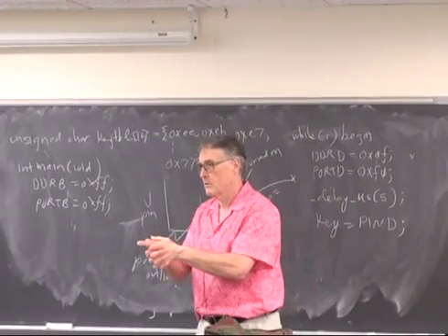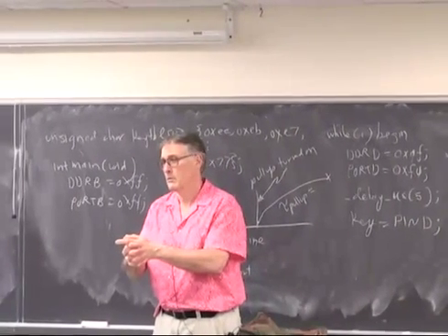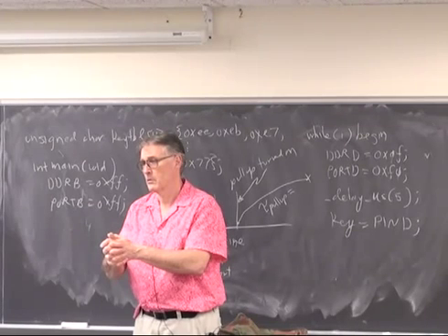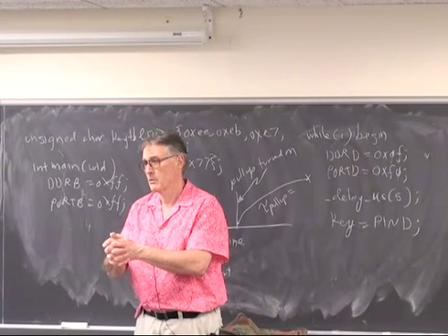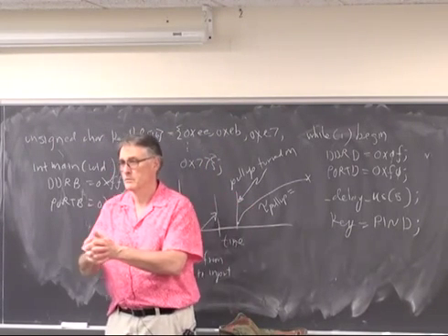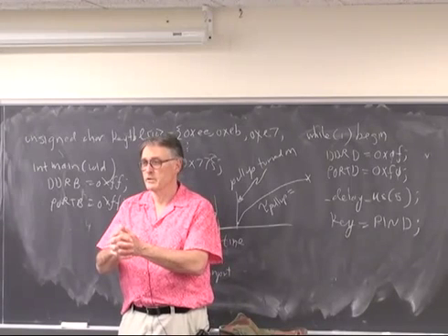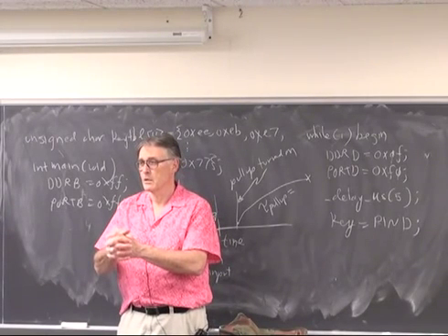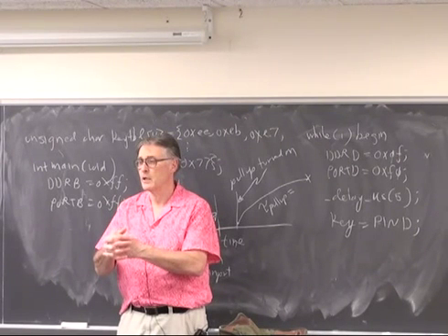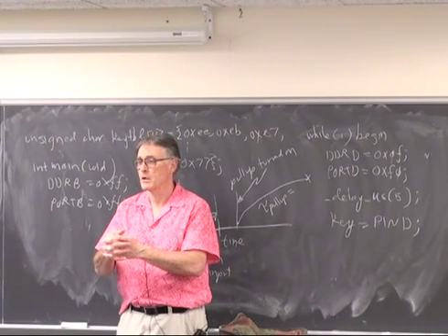Yeah, to measure the frequencies, we will use the timer 1 input capture register, but it's not necessary to use the ISR to calculate the difference. It is necessary to use the ISR. Because how do you know when a new capture is ready if you don't use the ISR?